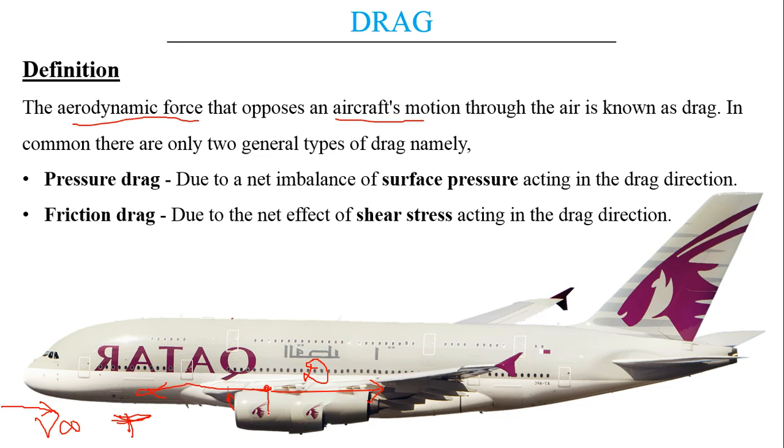Next we will be having weight, that is, the whole aircraft has some mass, and this mass acts at a particular point, and gravity attracts this mass from a particular point known as the center of gravity. So here we have the weight, and to counter this effect of weight, we have lift, which is generated by the wing. So lift here is perpendicular to the free stream velocity. The line for lift may be slightly tilted.